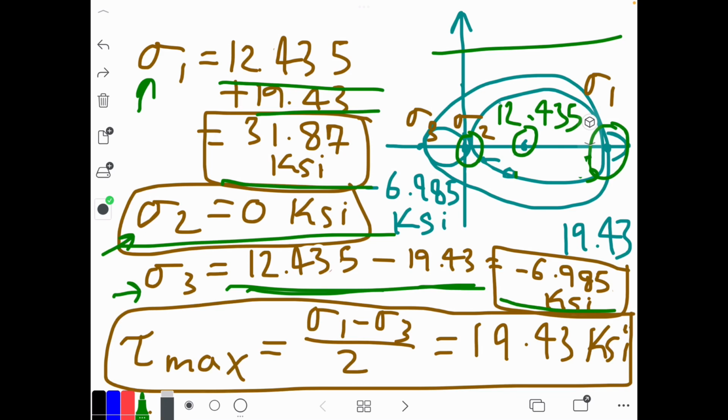Because this is negative, we have to think about something. When you're doing these state element stresses, you're thinking 2D, not 3D. Since we're doing this in two dimensions, we're getting rid of the third dimension that we had in the bracket, so one dimension is 0. This is why one of the principal stresses must be 0.